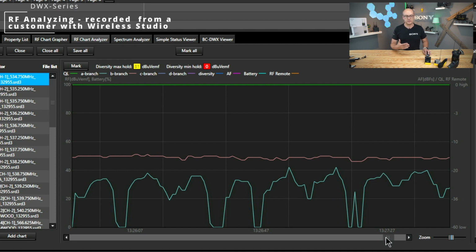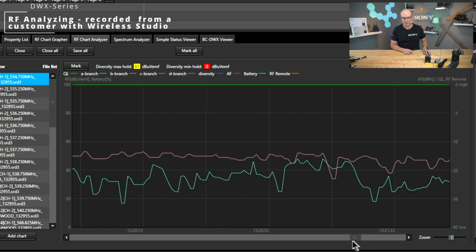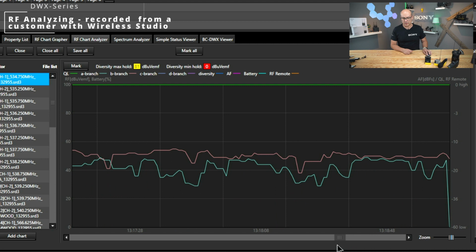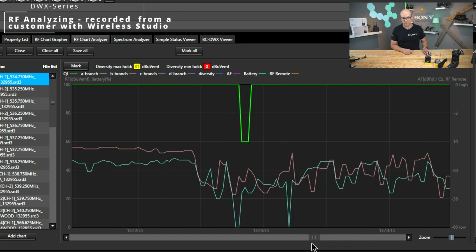I see this if the antenna is 50 meters away, but the other antenna has massive drops. So I think this antenna has an even bigger distance to the transmitter. You see the antenna A, the red one, is going down to 20, and 20 dB signal-to-noise ratio is the minimum the system needs to find the bits and bytes in the data stream.